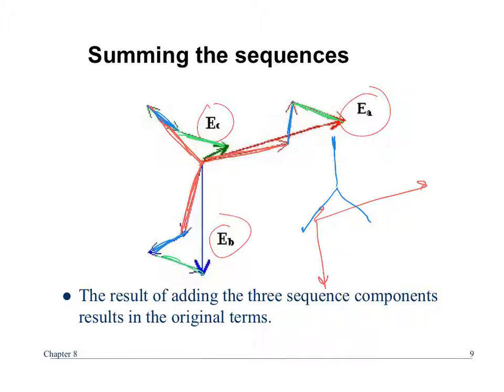Now again, we go back to looking at per unit, right? Per unit is a lot of work, but it makes our lives so much easier doing all this analysis. It's the same thing here. When we have unbalanced systems, we can certainly look at monitoring the magnitudes, but how much ground fault current do I have? This doesn't help me with that. I'd actually have to be monitoring the ground. That's a great question. Do I actually have to monitor the ground to tell what the ground fault current is?